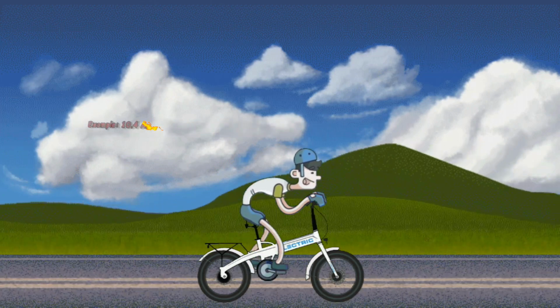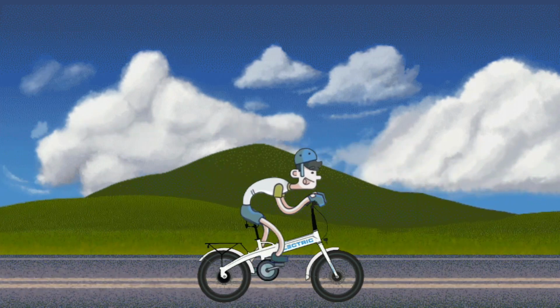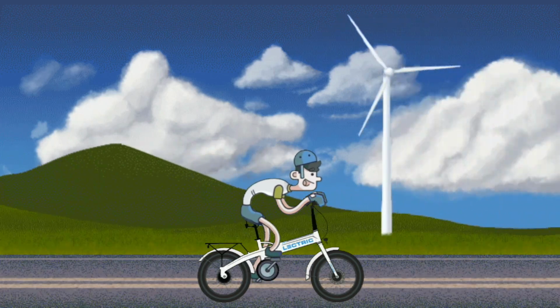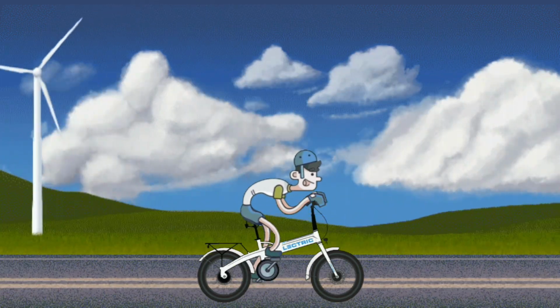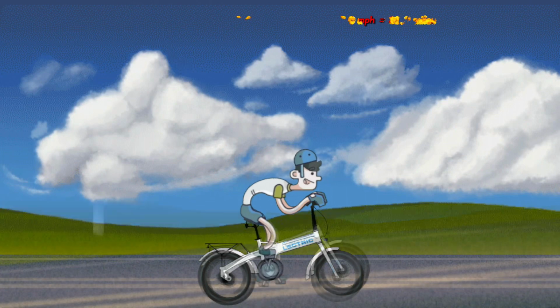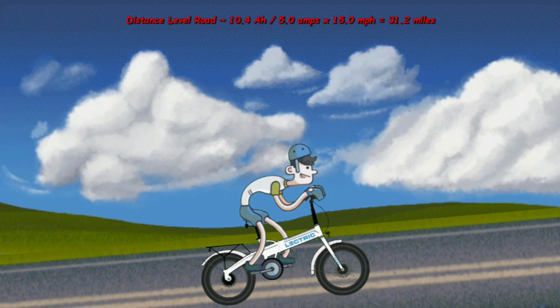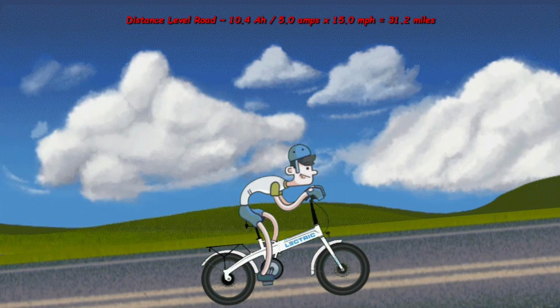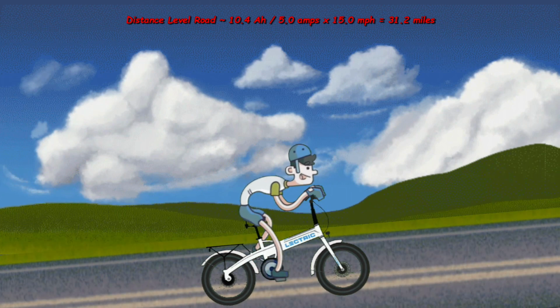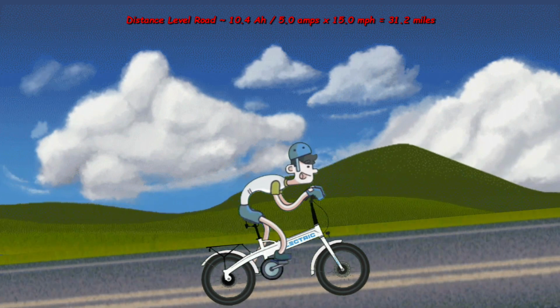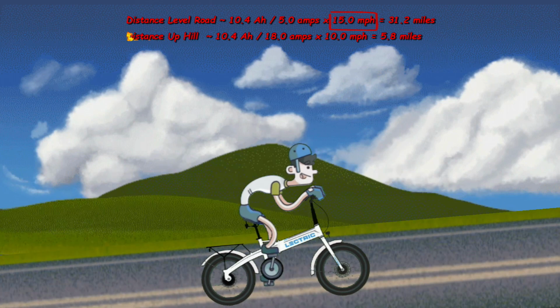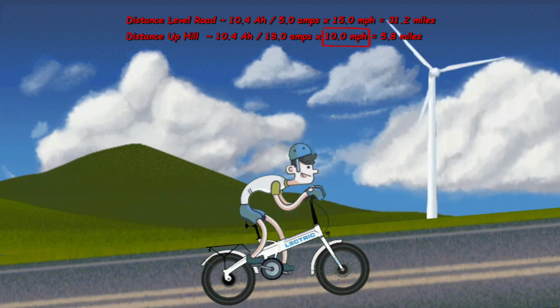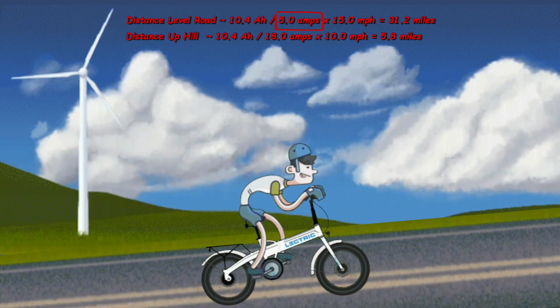Let me try to explain why riders have such a problem in trying to determine the range of an e-bike. I will create a scenario using my distance formula. A rider comes to a mile-long hill, and he is in PAS mode 3, on level road, with no wind. While proceeding up the hill, he notices that his e-bike's speed dropped from 15 miles an hour down to 10 miles an hour, and that the current to the motor rises from 5 amps to 18 amps.